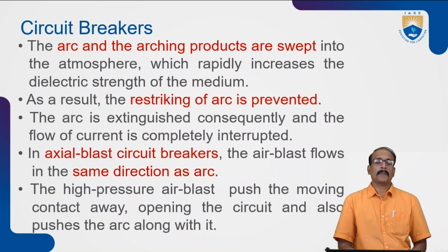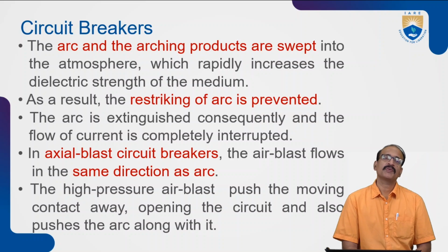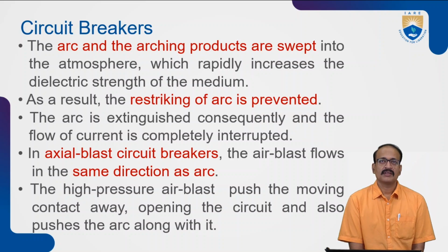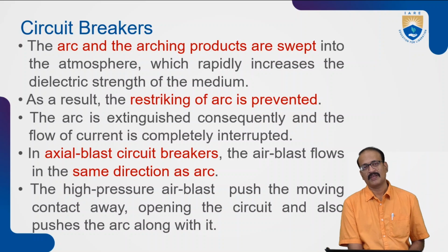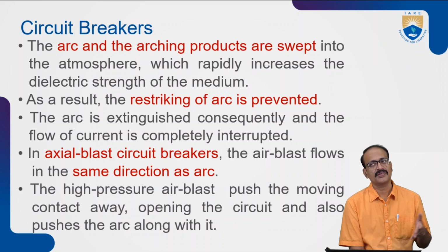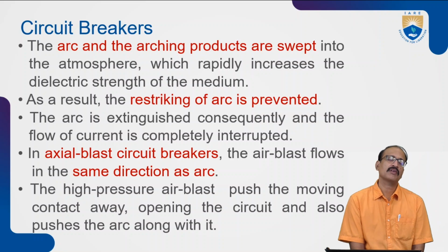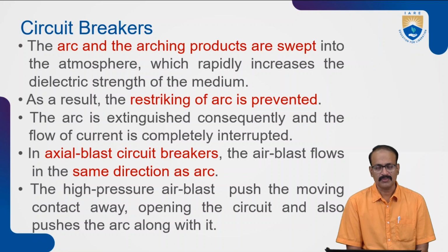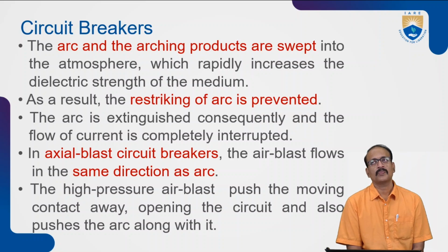Here, they are swept into the atmosphere. Once they are swept into the atmosphere, the normal dielectric strength of the air will come into the picture. Because of the high potential of the fault or short circuit, and also the ionized particles, the arc is occurring.